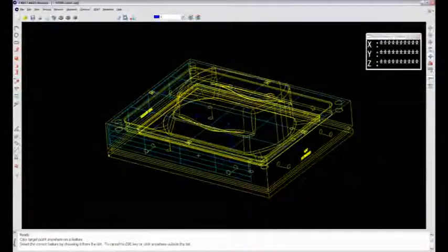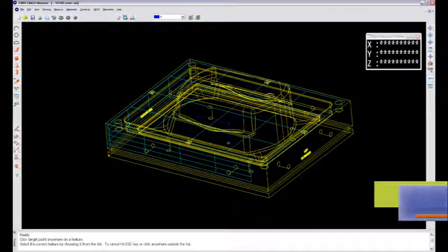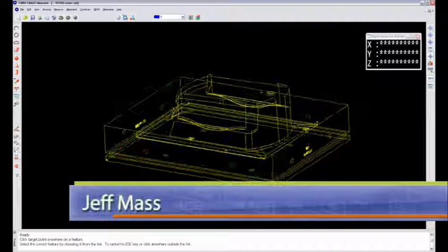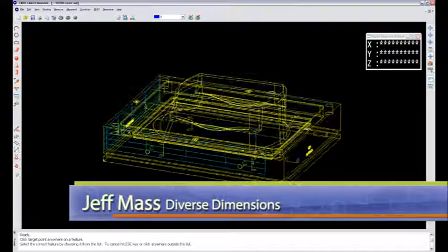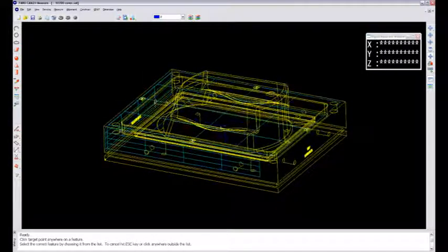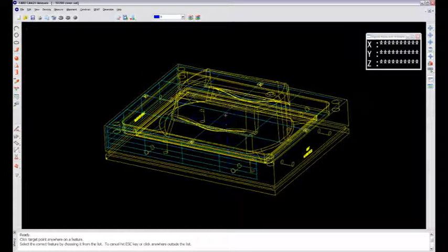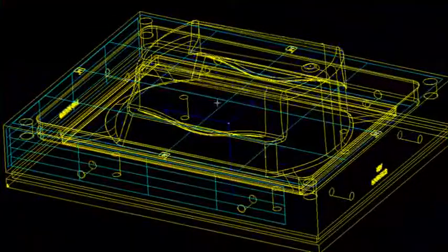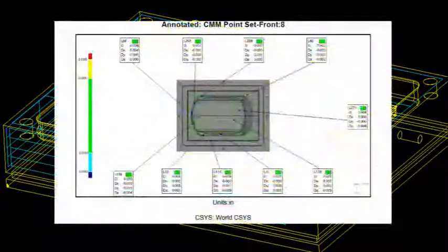I've just completed this measurement of this tool here. This is a Kohler tub, and I've peppered it with some surface points, and I've constructed some planes on the side here and have done an iterative alignment to this so I could do the CAD model comparison. With this client, what I'd like to do is give them a color map deviation report out of our GeoMagic system. And the way we do that is with these individual surface points.